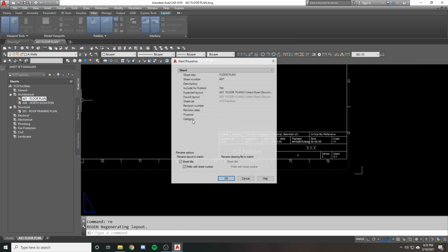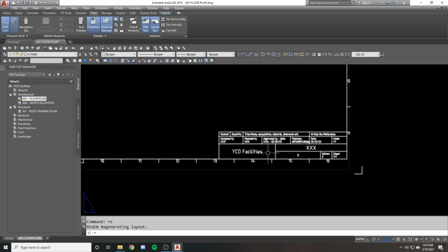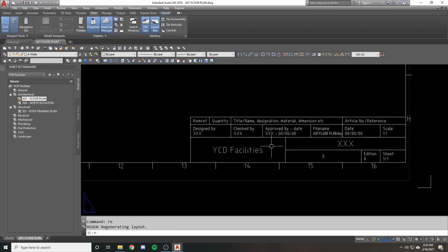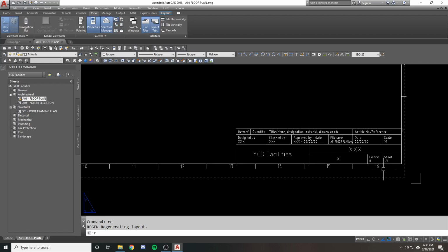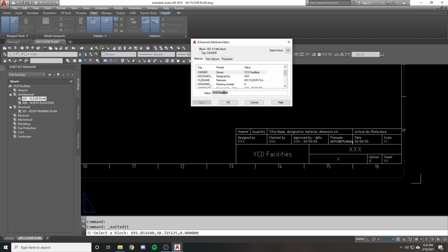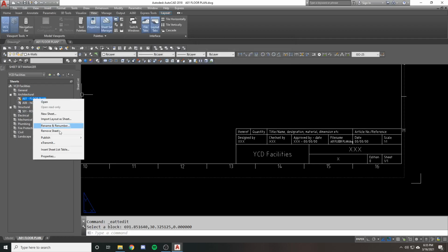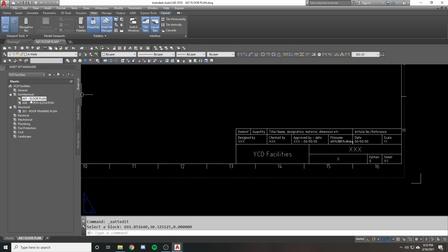When you are in this properties menu, and I'm trying to reiterate this, and I wish I could show you. I didn't have all these set up, and I probably should have, but you'll have information you can enter in here, and then when you hit OK and you go back to your drawing and you regen, all that information will show up automatically. They're smart fields meant to pull information from the sheet set that's tied to each other. You don't have to worry about creating it right now, but I want you to know how to access it, and that's how you would access it, probably through the block. It's probably already set up through the block. You don't even have to do anything here. It'll just be set, and you just right-click Properties and enter the information there.